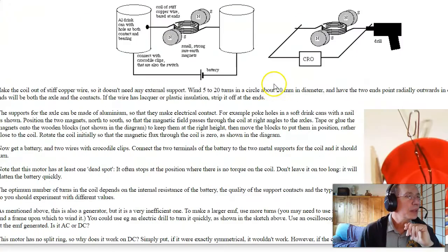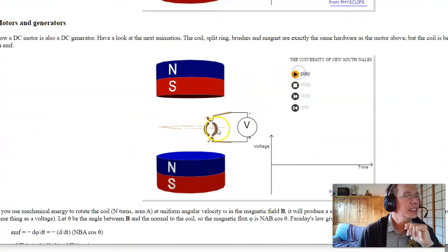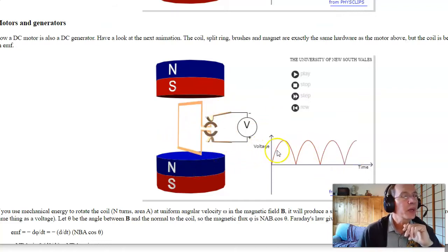DC motor, if I can find it, there we are. A DC motor has a commutator. What the DC motor does is when I get to that 0 crossing, I switch the leads, and that causes rectification. So this is actually a DC generator, also called a dynamo. From duality, apply constant voltage to the motor, and I'll get the speed. The higher the voltage, the faster it spins.